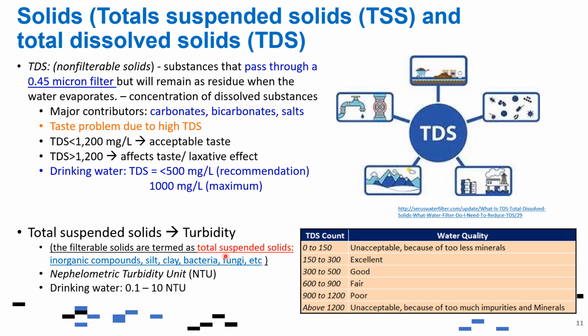All right. So basically, the suspended solids are things like silt, some clay, and some bacteria that make the water cloudy or not so clear. We have to at least know this kind of quality in order to determine what sort of processes we are going to use in a water or wastewater treatment plant. For turbidity, we can do some coagulation and flocculation, for example. And for TDS as well, we possibly use some reverse osmosis at the end to reduce the TDS further.